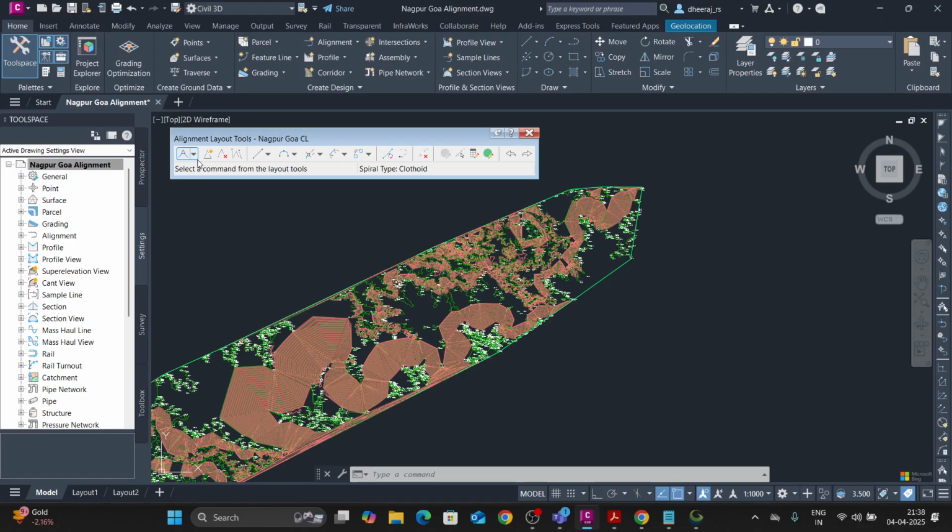These break lines have a function in the Civil 3D. Before the first break line, these are all the alignment creation tools, right? First one is create alignment. Then it is a PI, point of intersection of two tangents. By adding this, we can add this by clicking this. Then the third one, delete PI. If you want to delete any, you will understand this in the upcoming.